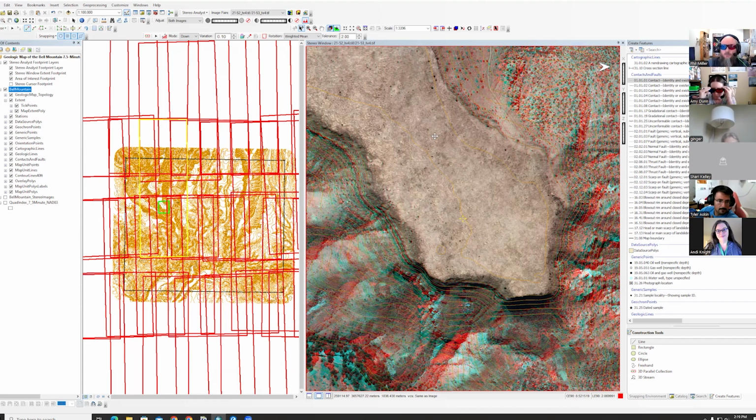If you're using the beam splitting technology, it will do a little bit differently because it's polarized, but it switches which pole cross is left eye and right eye. This button will allow you to invert the model. As you're bouncing around looking at different areas of the photogrammetry project, if the image goes inverted, valleys are ridges and ridges are valleys, you'll want to click the invert stereo model to flip those.